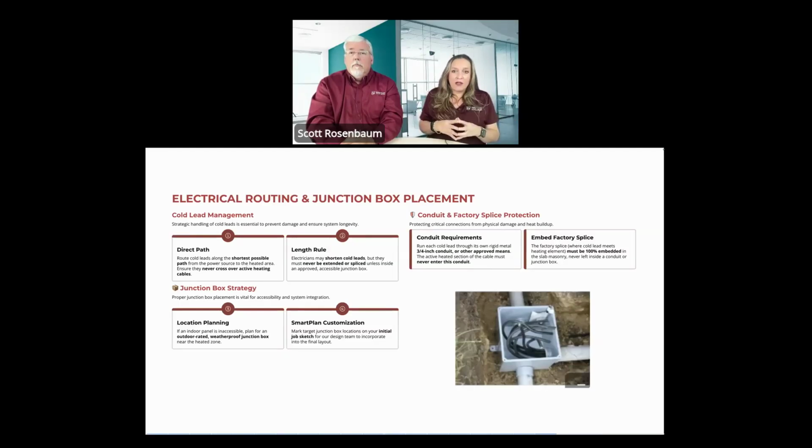So we do also provide, or we'll spec for you, the in-ground junction box, in large or small size, or the large wall-mounted junction box. If you're not putting it in the ground, and when we say ground, this is not something you drive over. This is off to the side, in the dirt, kind of in the landscaping. It is waterproofed so that those connections stay watertight, but we do want you to use the junction box, because that's how you would have to extend them. If you look at this picture right here, all of these wires have been trimmed to the correct length. The local code will tell you how long those leads have to be. So those leads have to be at least a certain length.